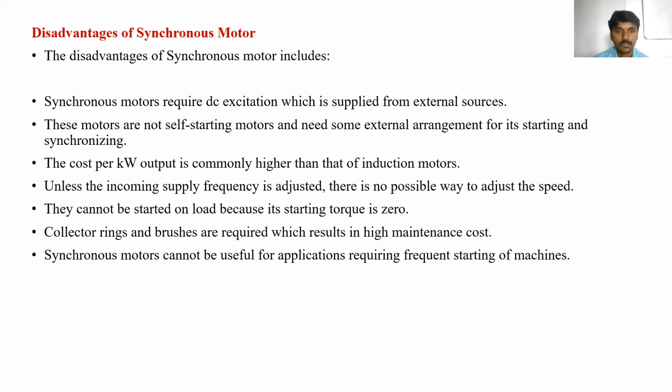They cannot be started on load because the starting torque is zero. Okay, if a very heavy load is applied in the starting condition, what happens? The motor may be damaged because it is not capable of producing that much starting torque. The starting torque is almost zero. That's why the synchronous motor cannot be used where a high starting load is required. Clear?